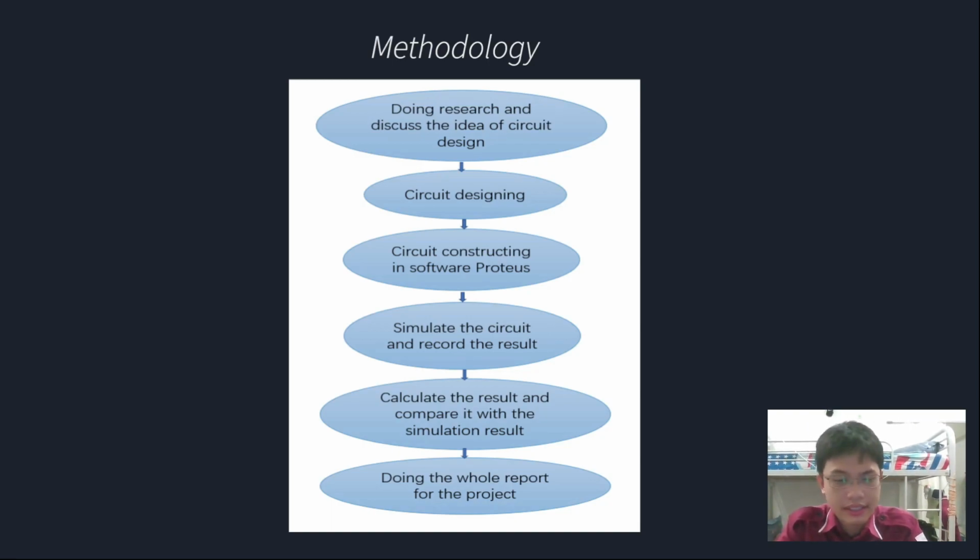After we finished our circuit designing, we used Proteus Professional as our software to construct our circuit. To construct the circuits in Proteus Professional, first we need to launch the Proteus software, and then create a new project with the default design template, without PCB layout and firmware project. Then we click on the label P, which means the device symbols, and select the 741 operational amplifier and resistor sequentially. Then we set out all of the components following the design and connect all of the components with wire.